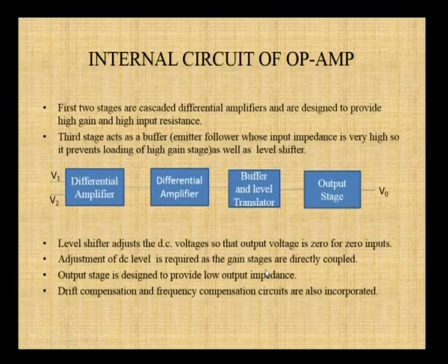If it has high voltage gain, then the amplitude of the output is very large even if the input voltage is in the range of nanovolts or millivolts. And if it has high input resistance, the loading problem will not be an issue. So you can use a very low voltage as a signal, and the output of the amplifier will be a magnified output.